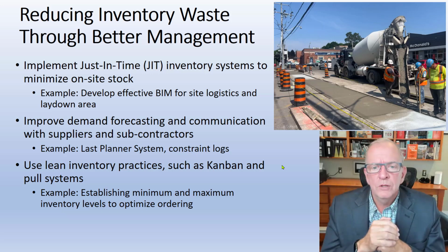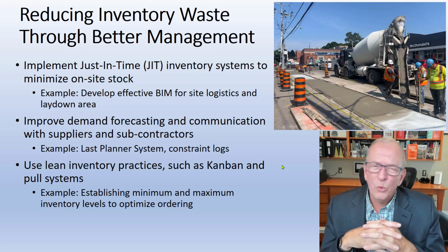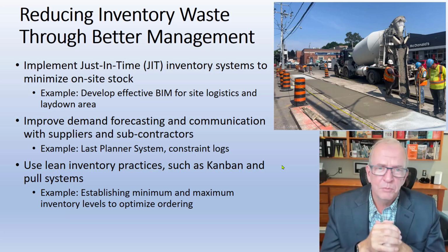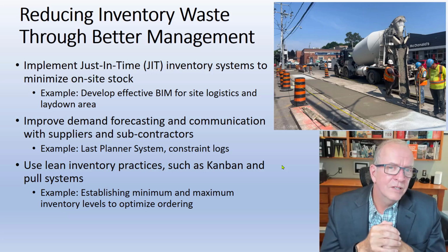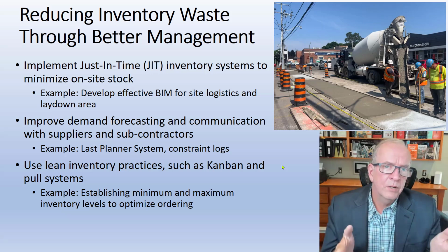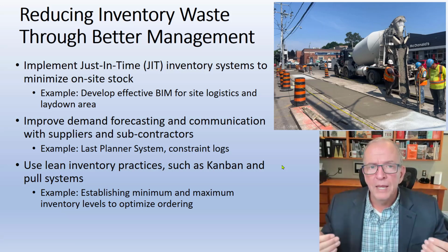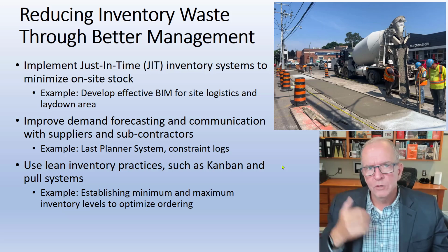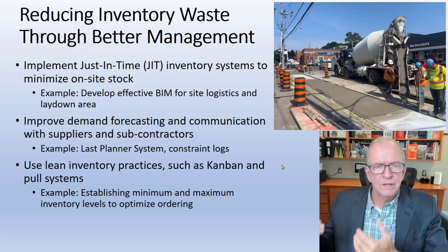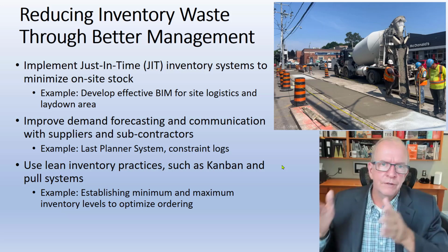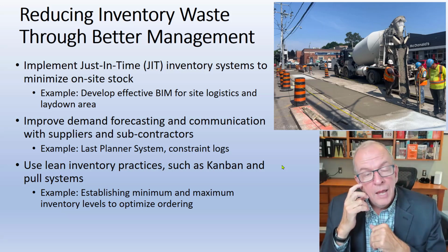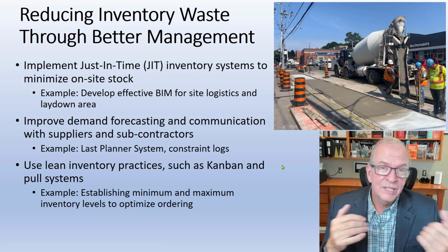Implement just-in-time inventory systems to minimize on-site stock. So what am I saying with that? Because I just said last responsible moment. Part of what I'm saying with that is have effective site logistics plans. Have them updated constantly, because a site logistics plan works for a period of time, but then as your project progresses, the availability of space changes on your site. So you have to look at the various stages and phases of construction and come up with the most effective site logistics plan. And that includes laydown areas and storage.